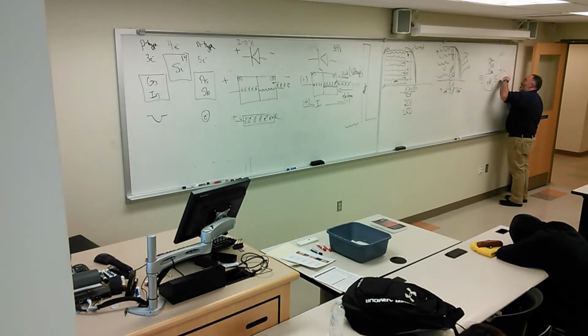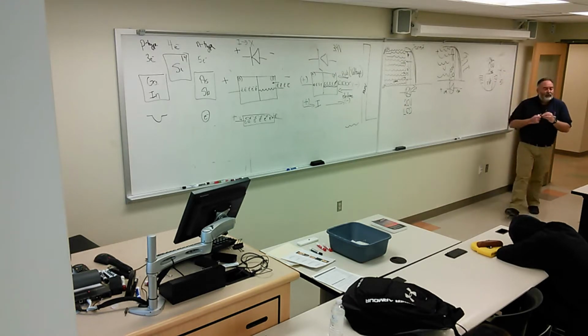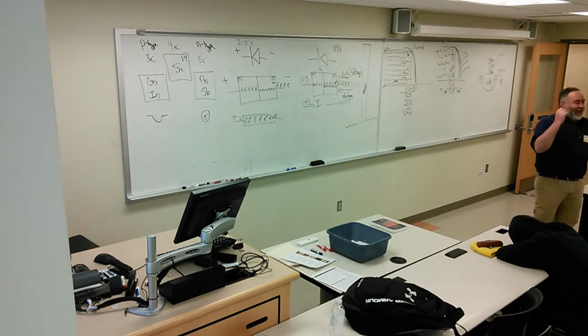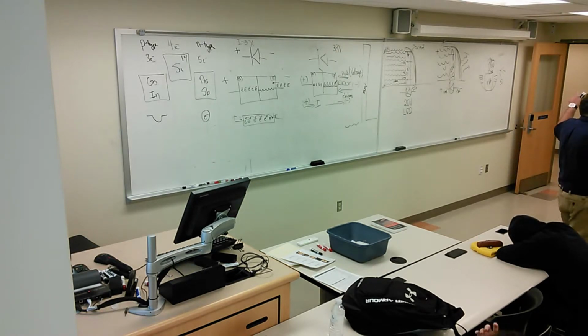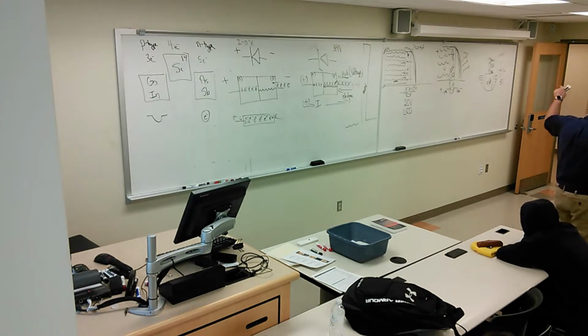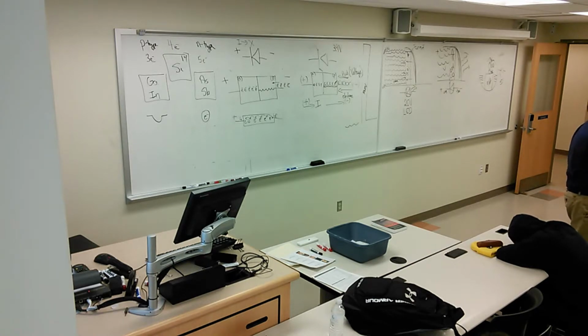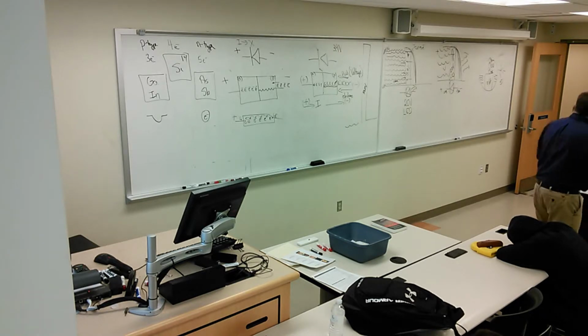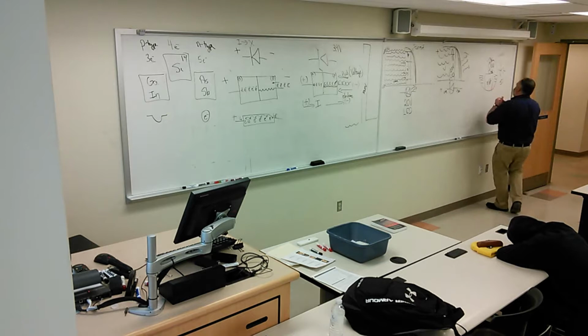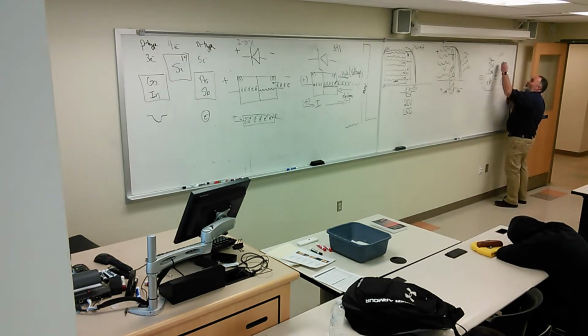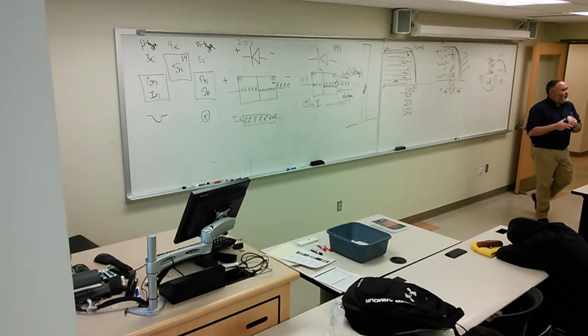pick a number, let's make it a 5-volt, is a 5-volt Zener diode. And that the LED and the low-battery circuit and all the other things, the smoke detector itself, only needs 5 volts. But you can't go to Walmart and buy a 5-volt battery. They don't sell them, I don't think. You can probably find them online on Amazon, but they're not a convenient thing. So you put a 9-volt battery in there. But even though the 9-volt battery is running, this guy's a 5-volt. As long as there's at least 5 volts, then the current will flow and the machine will work.